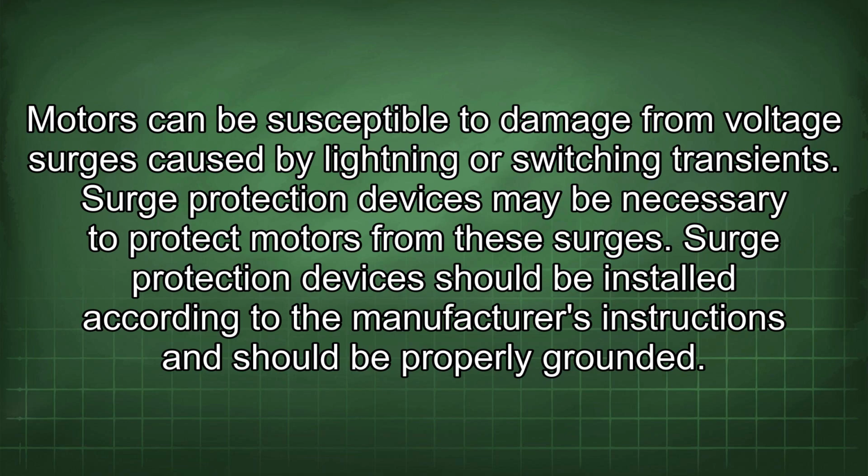16thly, the calculations provided do not address the issue of surge protection. Motors can be susceptible to damage from voltage surges caused by lightning or switching transients. Surge protection devices may be necessary to protect motors from these surges. Surge protection devices should be installed according to the manufacturer's instructions and should be properly grounded.